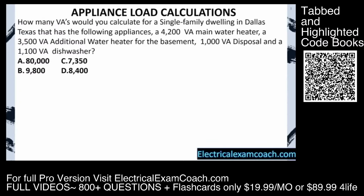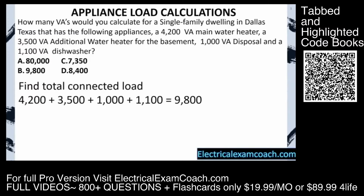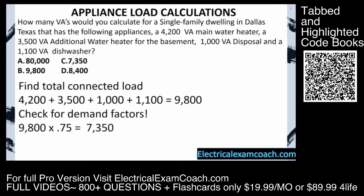How many VAs would you calculate for a single family dwelling in Dallas, Texas that has the following appliances: a 4200 VA main water heater, a 3500 VA additional water heater for the basement, a 1000 VA disposal, and an 1100 VA dishwasher? First, we're going to find our total connected load. We take and total it up, and it equals 9800. Now, we check for demand factors. Sure enough, we have 4 or more fixed appliances, so we can apply the 75% rule. We take 9800 multiplied by 0.75. That gives us a new reduced load of 7,350 VAs.